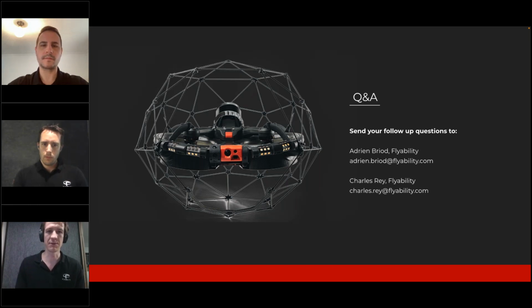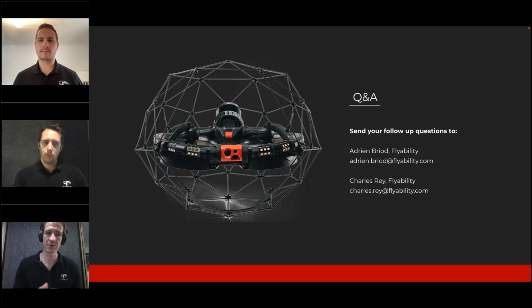But if you want to even measure the width of a crack, you know that you have that resolution that can help you. And if you want to measure the length of the crack, we have a 2D measurement feature as well, which was not the topic of Charles' presentation. If you're facing a wall and on a single image you see the full crack, you can use a tool to do a 2D measurement where we use a distance sensor to convert the pixel sizes into millimeters.